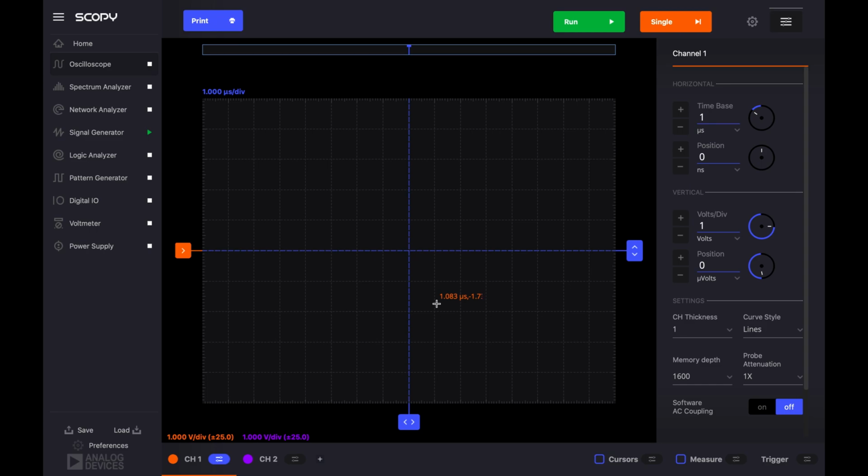The y-axis is voltage. When you're using a digital oscilloscope, really what it's doing is exactly what you would do in the early labs with the voltmeter, where you take a measurement, write it down, take a measurement, write it down, except instead of you doing that once every couple of seconds, the scopes in the lab, for example, can go up to, I don't know, 10 to 20 gigasamples a second. You heard that right. That is 10 to 20 billion voltage readings per second.